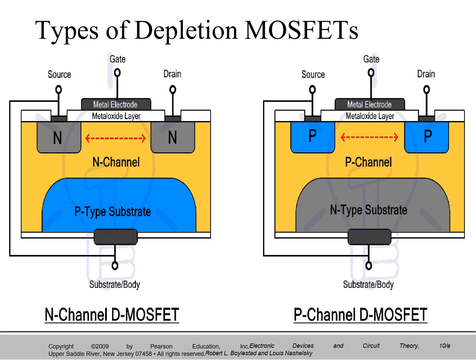Depending on whether the channel material is N type or P type, it is called N channel or P channel semiconductor material. In case of N channel, there are two N plus regions linked by a channel. P type material is taken to form the base. Sometimes this is also indicated as the fourth terminal, that is substrate. A P type substrate is there, and from that an ohmic contact is taken, which can be called the substrate, sometimes also called the body terminal. That is the fourth terminal of a MOSFET.